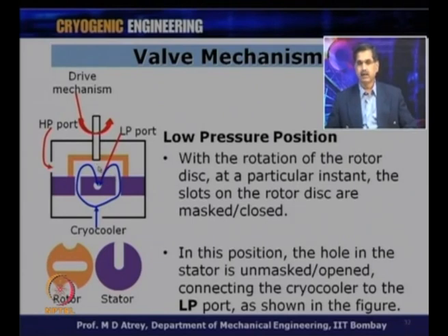This is schematically very simple for me to explain, but it is not very simple to fabricate and demonstrate in practice, because many times you can find that you have high pressure over here, low pressure here, and there could be some clearance, there could be some leakage past this if the rotor and stator are not very hard pressed over here.